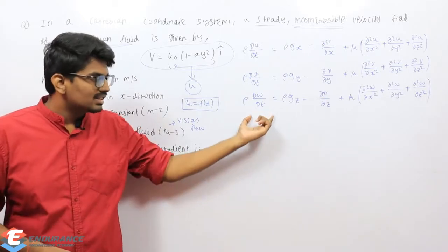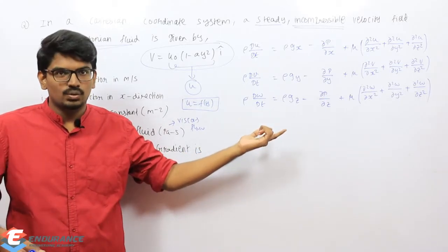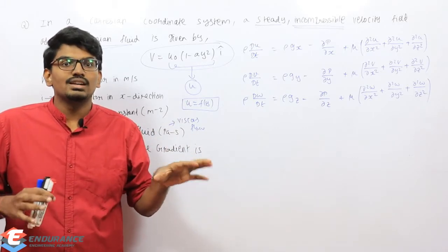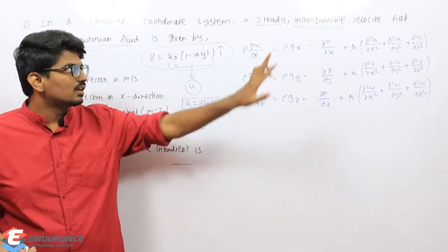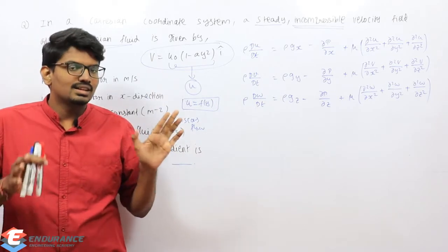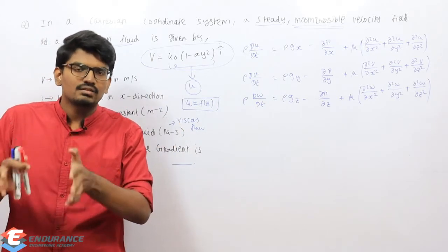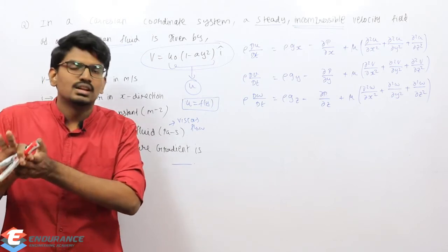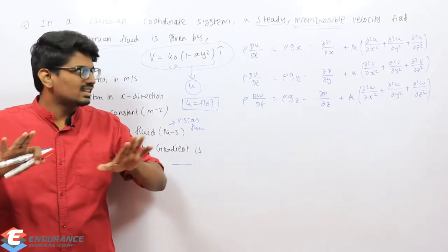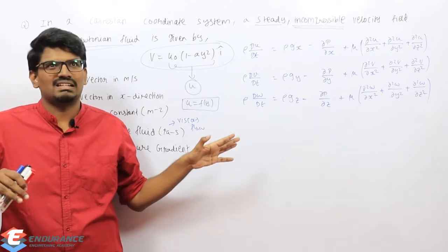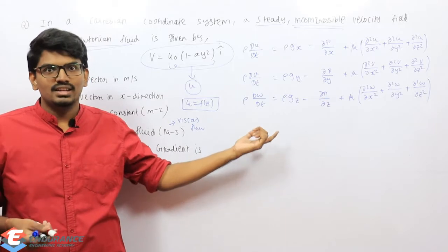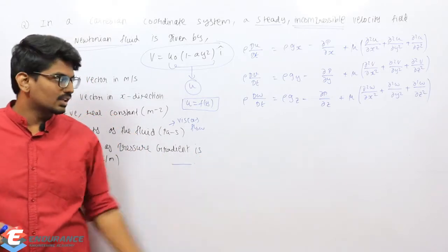So if I expand this material derivative, or total derivative, it will have a temporal component, which will become 0 obviously because they have given steady. But the convective component, which depends on space, is not going to become 0. So this is the first silly mistake, a conceptual blunder, if you have not understood the material derivative.